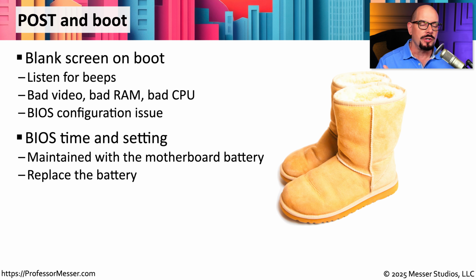If you're powering up and you get a message that the BIOS time and date is incorrect, then it's very possible your problem is with the battery that's on the motherboard. One of the few reasons we still have a battery on the motherboard is to maintain the date and time, especially if there's no power source to the computer.